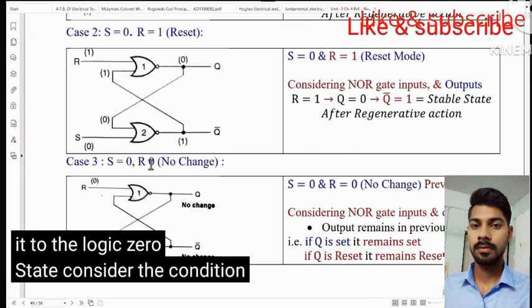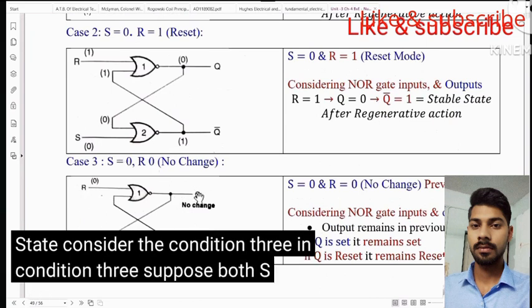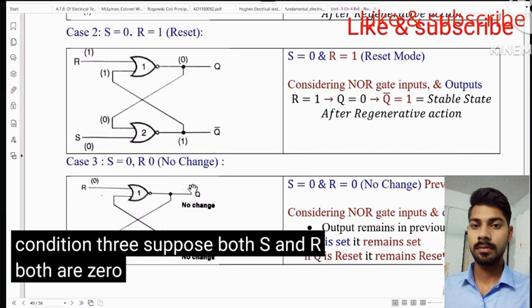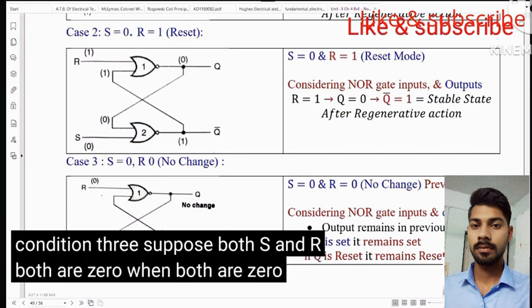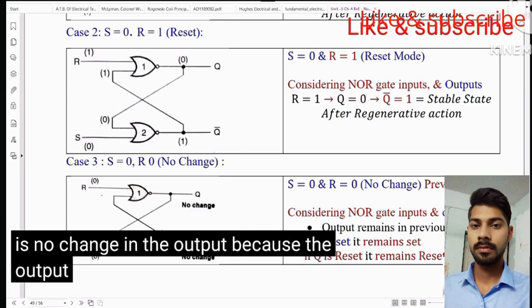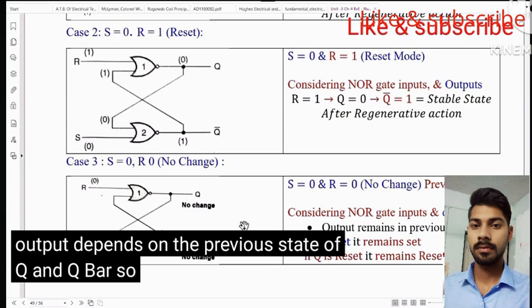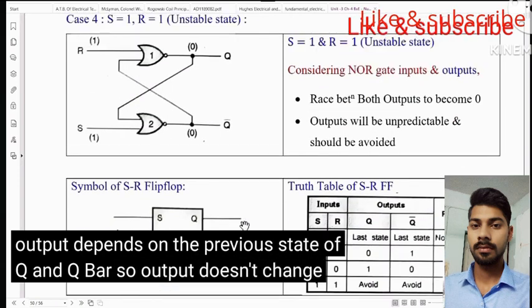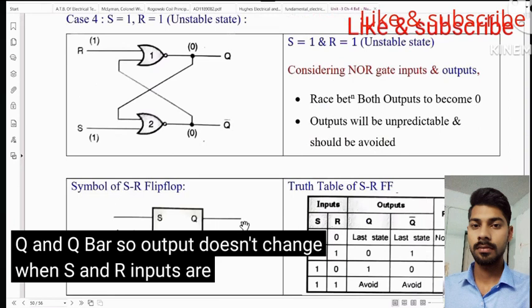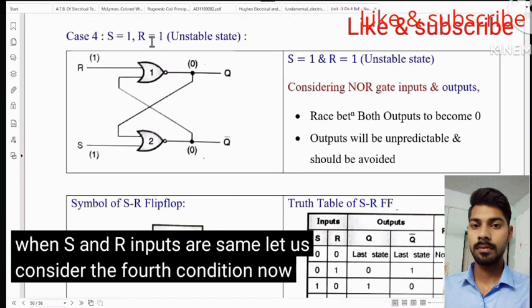Consider condition 3. Suppose both S and R are 0. When both are 0, there is no change in the output because the output depends on the previous state of Q and Q bar. So output doesn't change when S and R inputs are the same. Let us consider the fourth condition now.